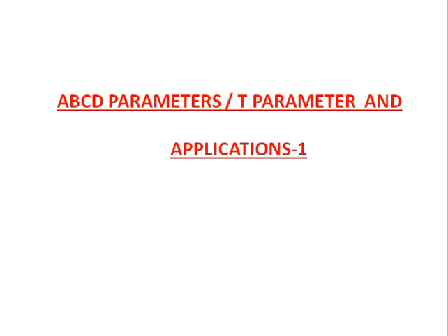There are some limitations of using ABCD parameters in electrical networks. ABCD parameters are valid for linear networks only. They cannot be used for non-linear networks. They are used in modeling of transmission lines.